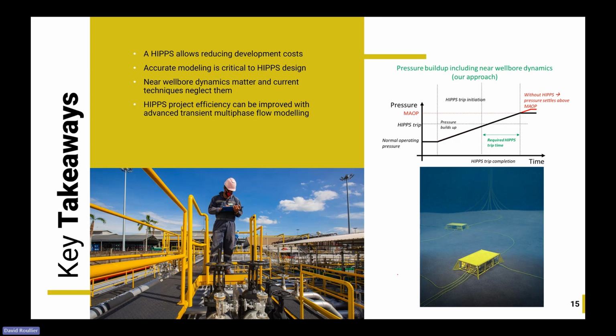And to be clear, the near wellbore model we've developed has been for single phase or at least liquid flow in the porous media. Multi-phase hasn't been addressed. However, subsea, deep water, I have yet to see completion bottom hole pressure below bubble point for oil system. Of course, if you have condensate or gas system, it's the case. But this is more applicable for oil development for now. But we do see potential to expand it to even multi-phase.